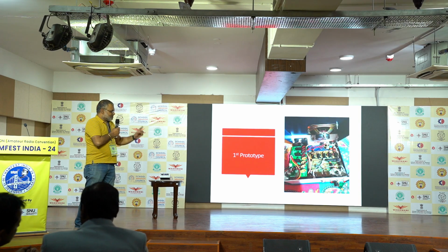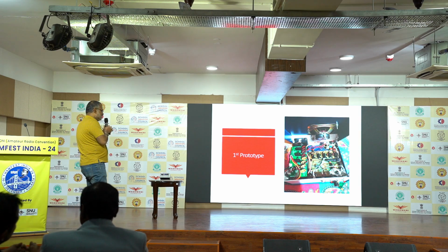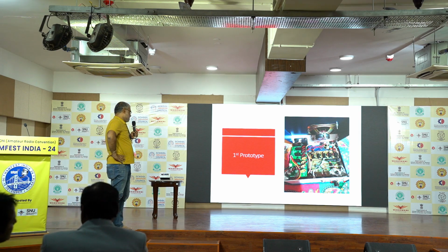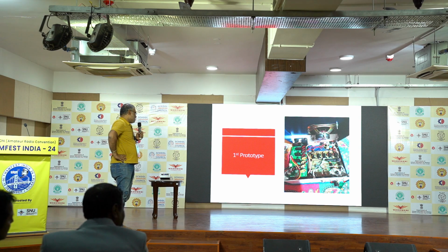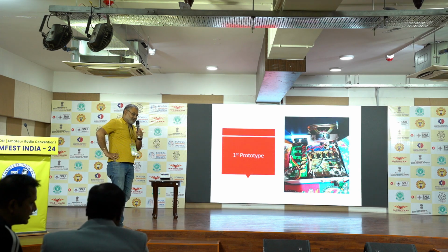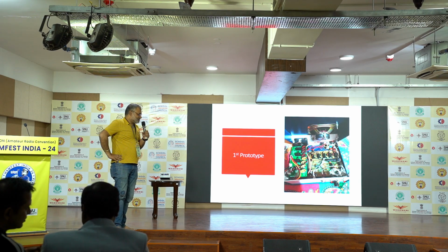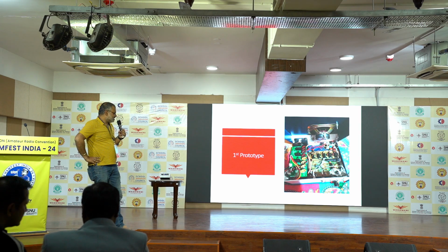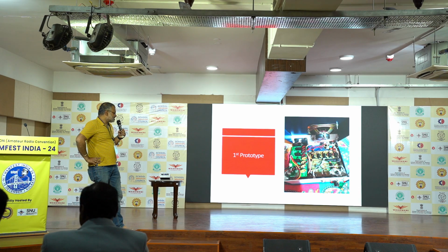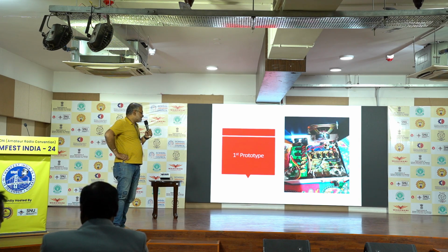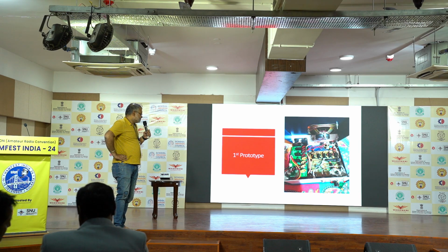Next. Okay, this was the first prototype which I built 2 years ago. Looks good? Not good. Yeah, it worked. It received signal, it sent out signal, but it was very noisy. Why? Because I was using all through-hole components, and I think because of that or something else, it was generating a lot of noise. But it worked.